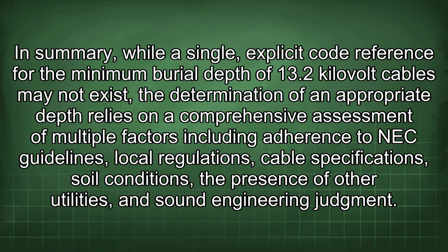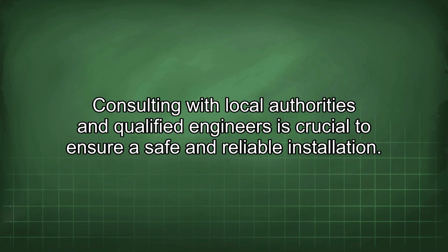In summary, while a single explicit code reference for the minimum burial depth of 13.2 kilovolt cables may not exist, the determination of an appropriate depth relies on a comprehensive assessment of multiple factors including adherence to NEC guidelines, local regulations, cable specifications, soil conditions, the presence of other utilities, and sound engineering judgment. Consulting with local authorities and qualified engineers is crucial to ensure a safe and reliable installation.